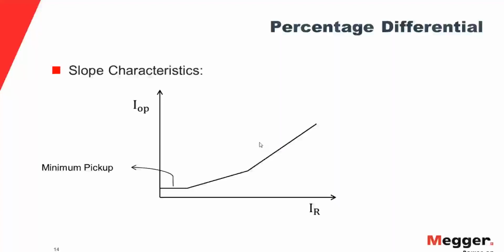Do you want to change the output context of the relay, or do you not want to change the output context? There are two schools of thought again, and it is up to the utility or the person who is testing it whether to do a scheme test or to mask the other elements, which is also called the element test.